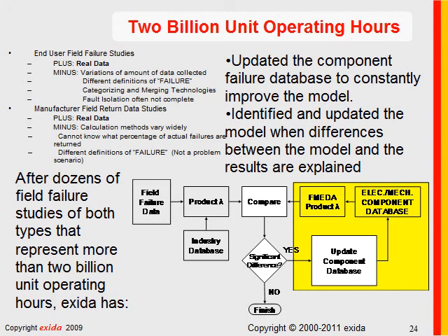I had one situation occur the summer before last where we were analyzing a two-wire sensing device. In the process industries, we call that a transmitter. And the failure rate numbers from the manufacturer's field failure study were significantly higher than the FMEA predicted.